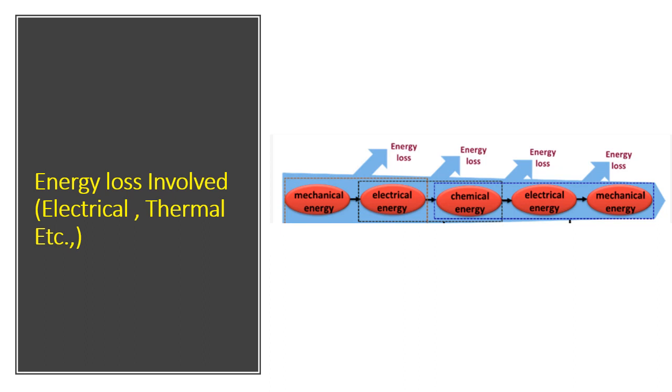Let's say an equipment running with severe misalignment takes 1 to 3% extra energy than a normal equipment. Similarly, it is the same case with equipments running with high unbalance and high vibration, maybe a faulty cable identified in thermography, a high temperature spot identified in a boiler or a process cyclones. They all contribute to a different sort of energy loss. So you can calculate the money involved in the energy loss and you can project it right away.